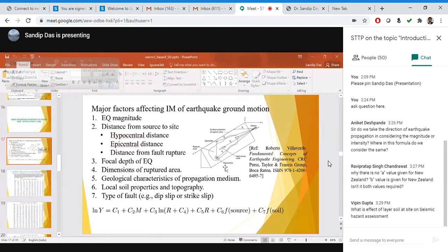But the attenuation model, I'm pretty sure that if your region is not seismically active, getting one developed specifically for that region is near impossible. So you have to find an attenuation model developed for a region where the seismicity is comparable, or the geology is comparable, and decide accordingly. Yes, it is possible. Of course, it is possible.